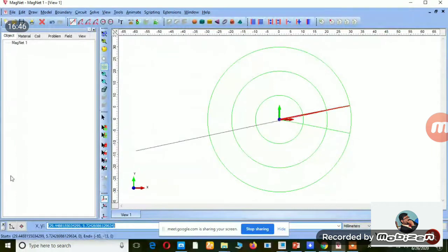So for that, what I am going to do, I just go for r comma theta, such that the r is now going to be changed into del r comma theta. So r means it is the total radius. Del r means that point is now considered to be the initialized point. Otherwise, I would give 0, 0, and then the origin would be the starting point. Now the starting point should be where I have the thread option. So this is the starting point. To get this as a starting point, I want to keep del r comma theta, right?